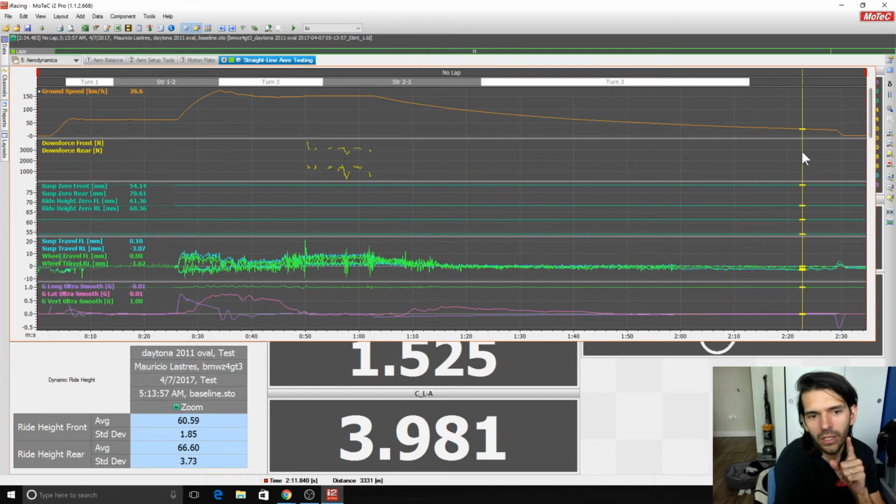And then towards the end, when the car is going very slowly, around the 20-something mile per hour or kilometer per hour range, we're going to calculate the mechanical friction in the system. Basically, the car decelerating just because of drag that's induced through the transmission and the tires and the hysteresis in the tires, and the drag through the entire system that's subtracted from the aerodynamics.